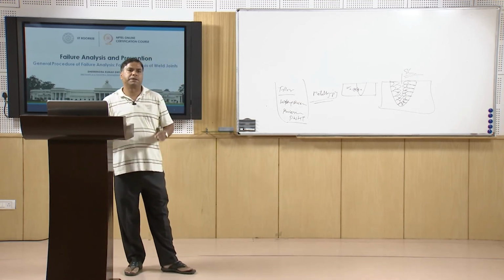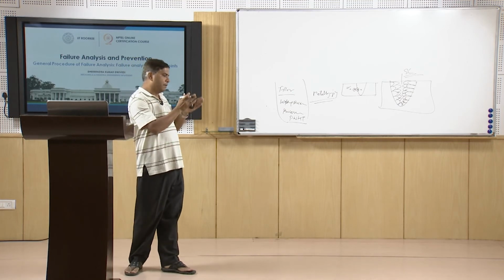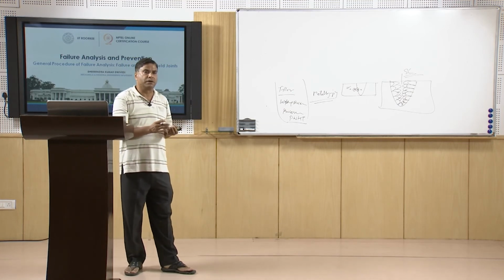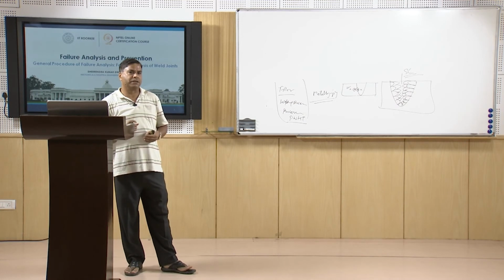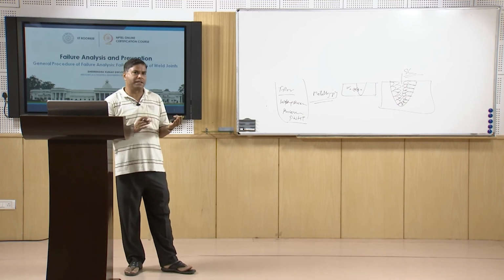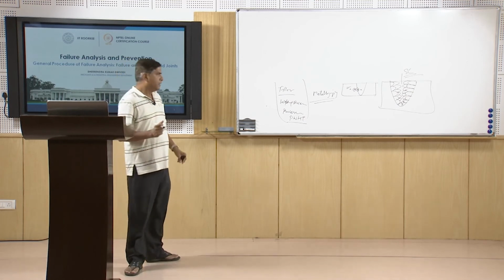Metallography can also help us to see if there is proper penetration through the thickness, or if there is a lack of penetration, or if the fusion of the base metal has taken place up to the appropriate depth or not. All that can be observed.